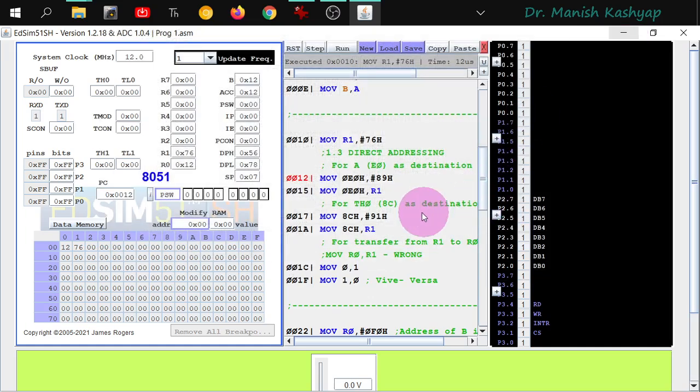Let us begin by simply putting something into a register, right? Here you can see that I have written this command MOV 0E0H, #89H. The 0 is prepended because the number begins with an alphabet instead of a numeric digit, and H is for hexadecimal. So E0 is the number that we are writing here.